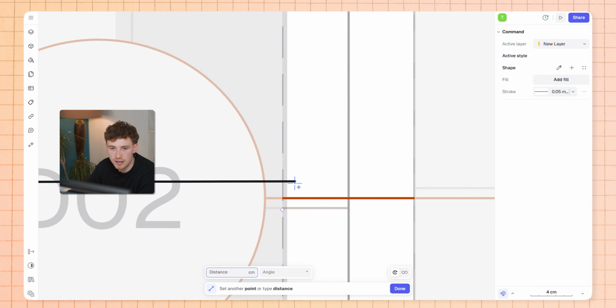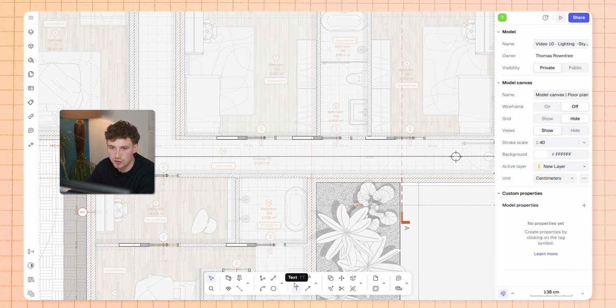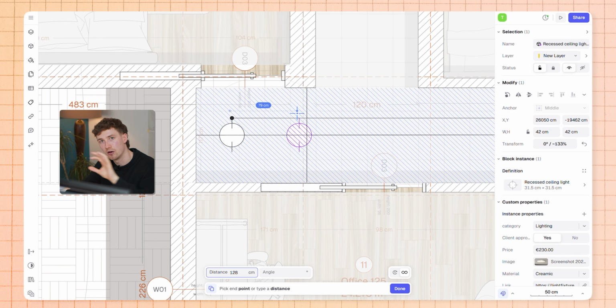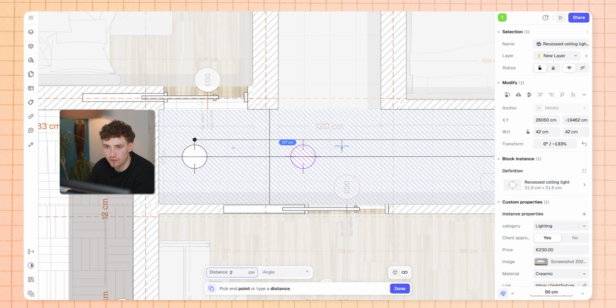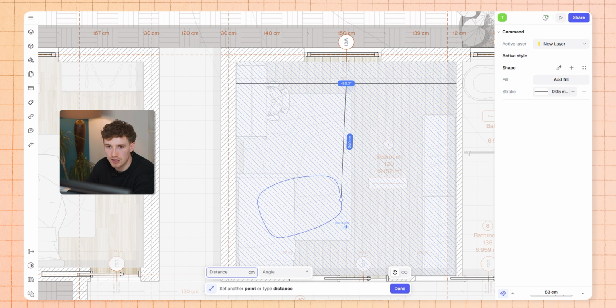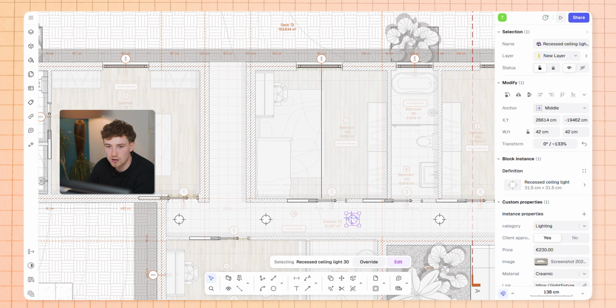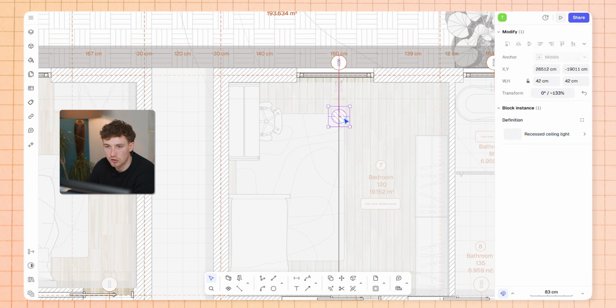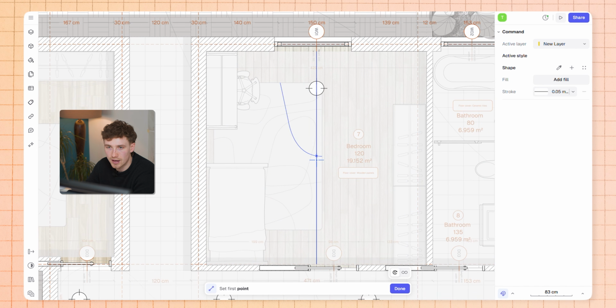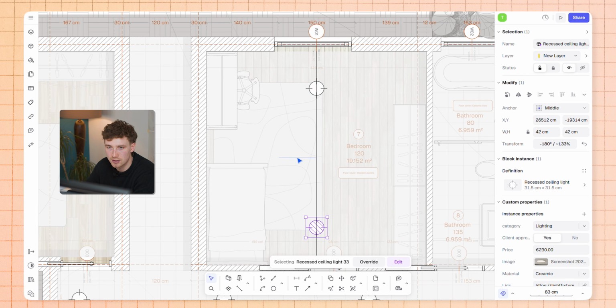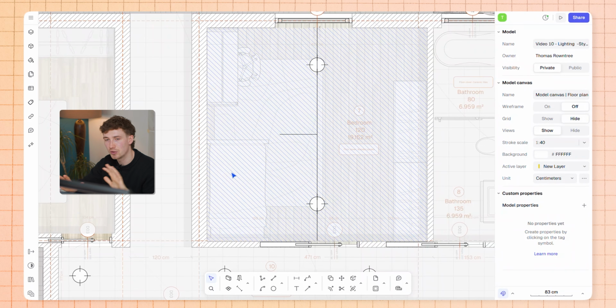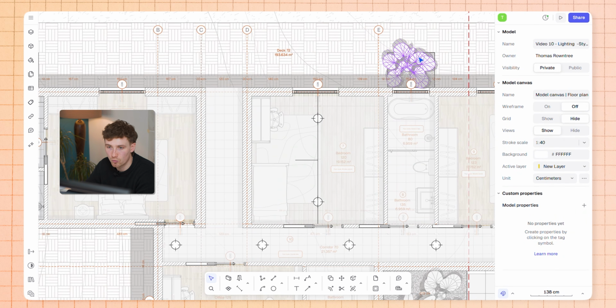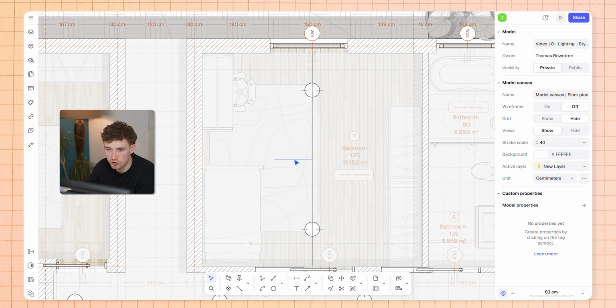And so what I'm going to do here is create a centerpiece to this corridor. This will mark almost like an anchor where these symbols are going to follow. This will make sure that the lighting fixtures are evenly placed across this corridor and that they're following a bit of a grid structure. And you can see here now, we can do that in the other rooms as well. So we want to centralize it to the rooms. In some cases, we can pull them off central slightly, depending on where certain pieces of furniture are. And so we're generating quite a clear and logical grid structure, and making sure the fixtures are located in the right locations where we want to illuminate certain elements.